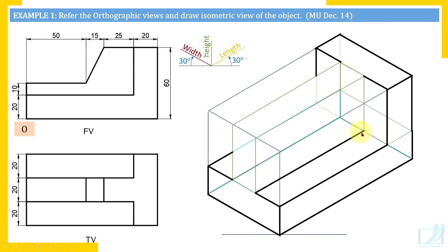Watch. So this edge, it is 90 mm long. That is total length is 110 minus 20. You need not measure that 90 mm because this edge is up to the vertical plate. So here it is. Then this edge. Then this 25 mm edge.